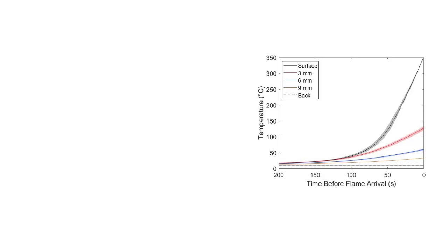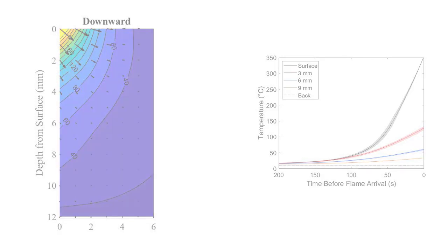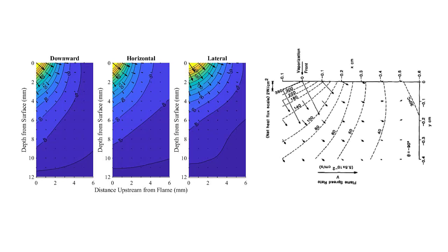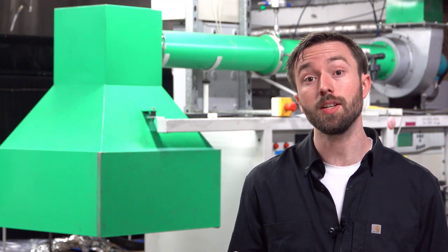Taking this repeatability in combination with the consistency of the steady-state flame spread rate, one is then able to retroactively reconstruct the temperature gradients ahead of the flame front using these temperatures. The results of the temperature reconstruction provide temperature distributions through the solid similar to those seen by Ito and Kashiwagi. This study therefore provides a method by which you can reconstruct the temperature gradients ahead of the flame front using relatively simple measurements. Then from these temperature reconstructions, we can calculate the relative contribution of gas phase and solid phase heat transfer across a range of experimental configurations.